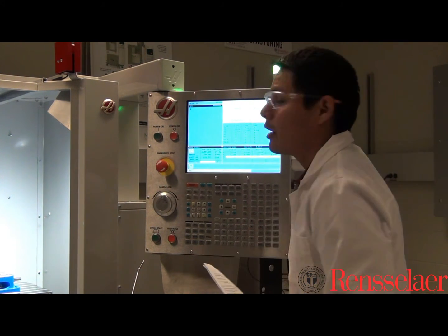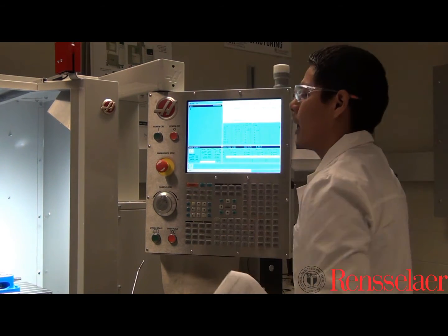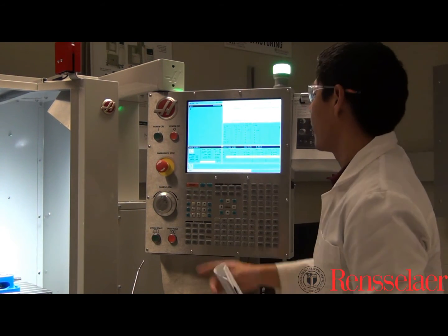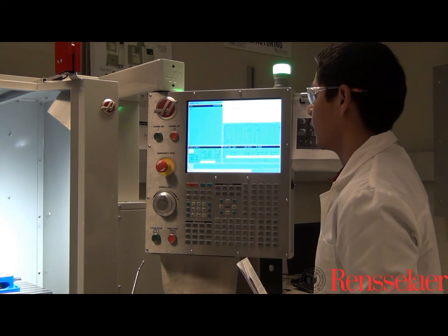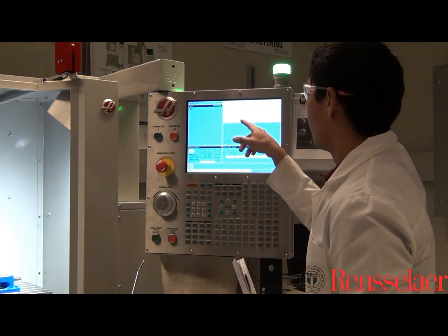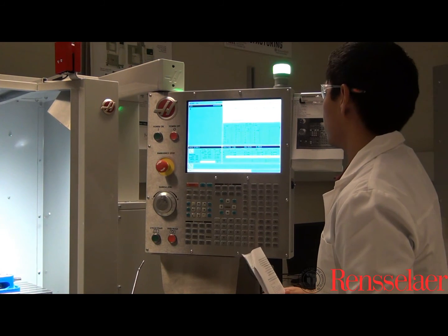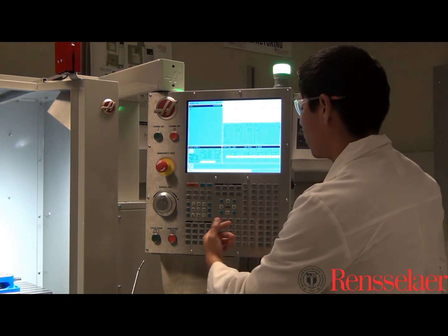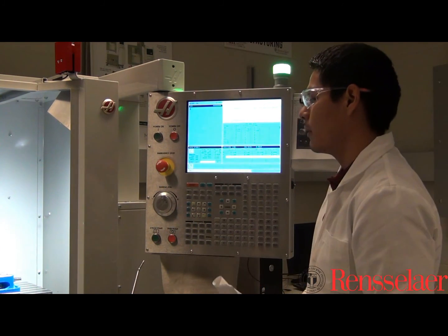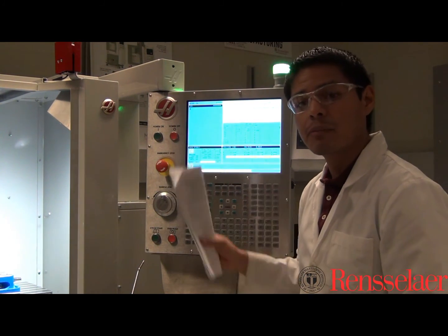slots. So now you got to make sure that you're highlighted towards the appropriate tool slot. So in this particular case, we're using the second tool, and that's why we highlighted the second row corresponding to the second tool slot. We then arrow to the length offset geometry. So now what we're going to do is press the tool offset measure button, and that number here indicates to the machine where it is when it first starts grazing the workpiece.